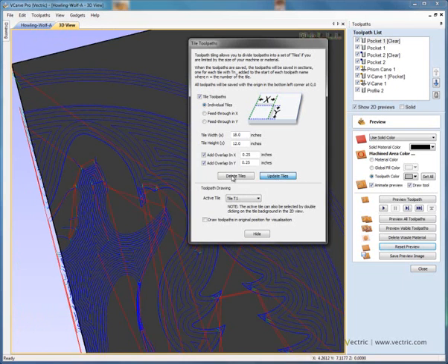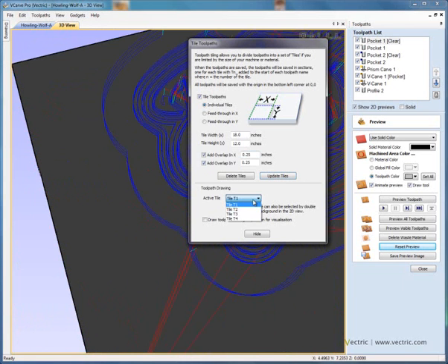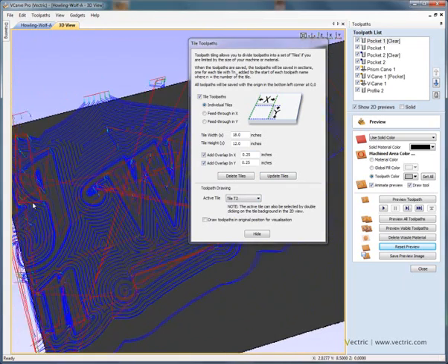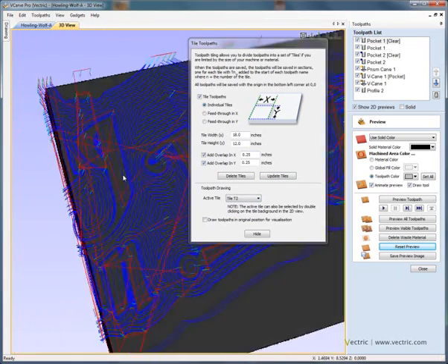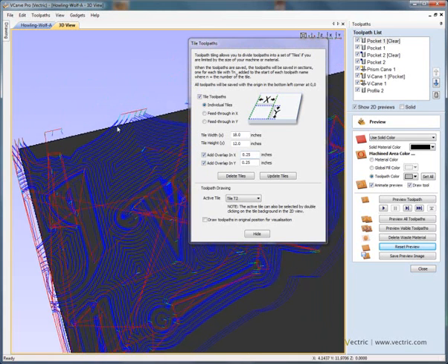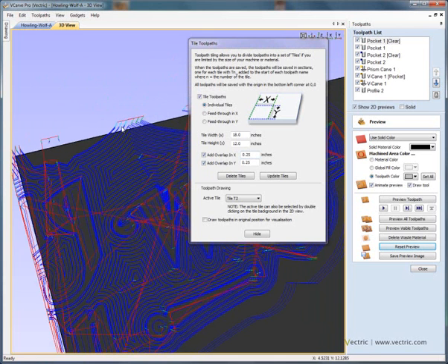If we say update panel, sorry, let's go back to tile number 2. There you go. So tiling number 2, this was the bottom right hand corner of the sign. We've said apply an overlap of 1/4 of an inch in X, so it's overcutting to the left by an extra 1/4 of an inch. It's also overcutting above by 1/4 of an inch.